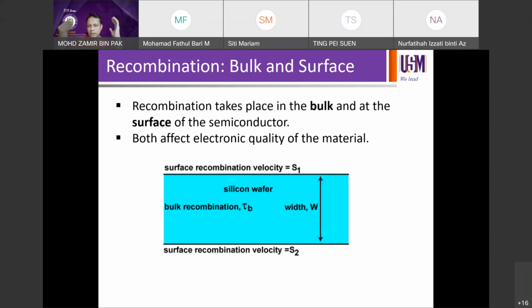For example, if you are a supply quality engineer controlling the incoming wafers before they go through all the fabrication processes to produce your transistors, then you should be controlling the incoming material quality to meet at least, for example, 500 microsecond lifetime for every single wafer. If it's coming at 700 microsecond, it's good. 500 microsecond is good. 300 microsecond, reject. Those are the things you're going to be dealing with when it comes to incoming wafer quality, especially if you're working in the QA department and you are responsible for controlling the incoming material quality.